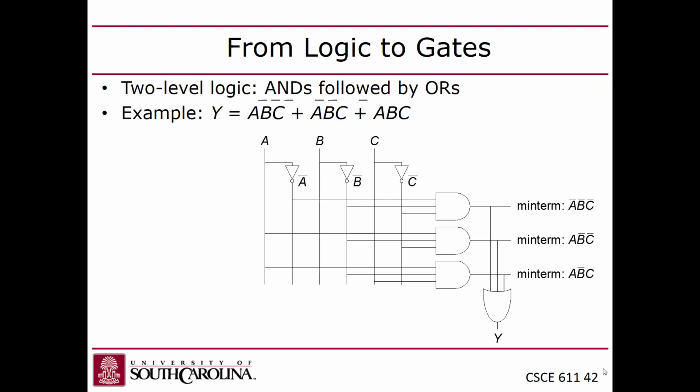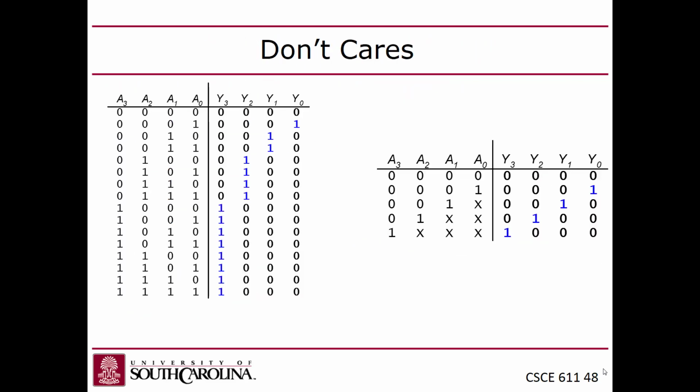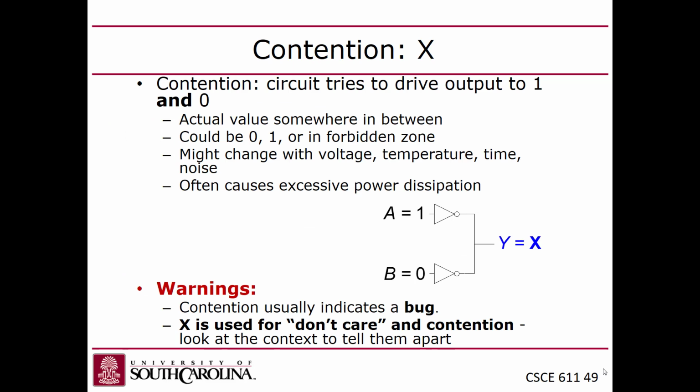So when you simulate and you see an X, that usually means that you have, they call it contention in the book. I always called it double driving. It means you're double driving a wire in your design, right? You with me? And you might think, well, how easy could it be to do that? Well, it actually is pretty easy once you start writing code in Verilog. We'll get to that a little bit later.